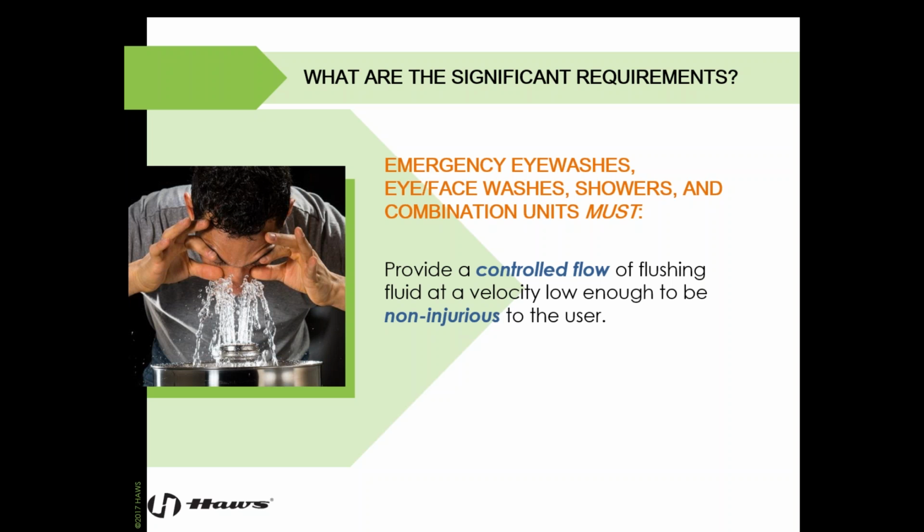body. It's important to provide for eye washes a soft, even flow to promote the use of the equipment for the full 15-minute flush. That's on the manufacturer as well as the installer to make sure we installed it at the correct PSI. It's being checked on a weekly basis to ensure that if an incident occurs, we do have that proper flow with flow rates, flow controls and a nice uniform flush.